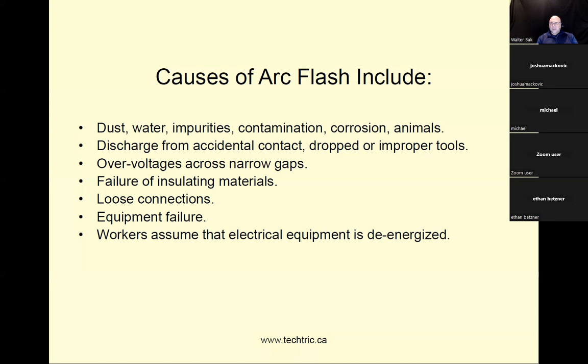So it's also a common procedure to have actually a human being standing there, sort of like an attendant, just standing there and making sure that there is no idiot that is going to come over and say, oh wow, who turned this thing off, let's turn it on, bang, and then you go goodbye, right? So it's a common procedure to have an attendant at the electrical panel, making sure that nobody accidentally turns it on because they think that it should be turned on.